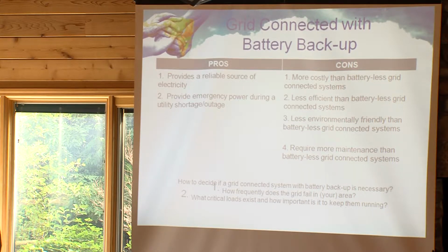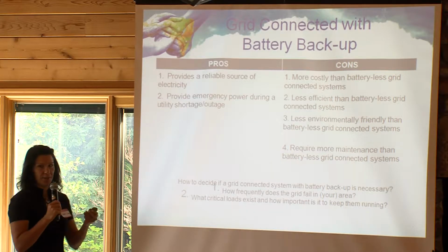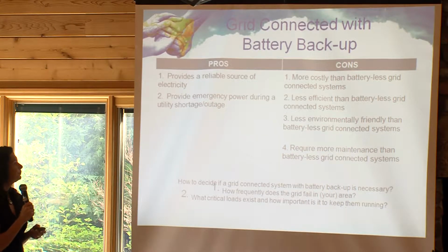And which parts do we want to make sure that in the event of emergency, that's that critical load, we want to make sure that there's constant supply of energy. Maybe there's a small data center, you don't want the threat or risk of failure or loss. Maybe you have a large kitchen because part of your church functions is to feed a lot of people and there's a lot of food in there. You have to think about these things. The critical load is really where it becomes important when you're sizing your battery banking system.